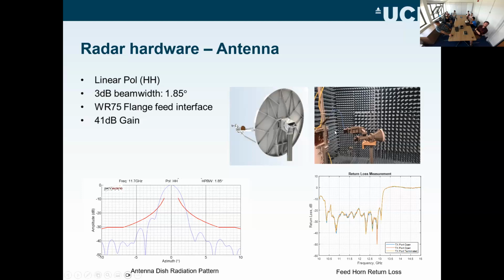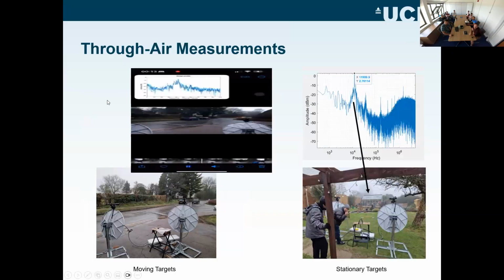I did some testing on the feed itself, because these feeds are designed for communications that have one frequency band on one feed and the other frequency band on another feed. For radar, we're using the same frequency band, so I wanted to make sure what happens on the other port if you feed one port, and whether it terminates or not. Some testing was done in a chamber with different scenarios, and those results are all validated. So once you've got all those pieces together, that's when the fun starts.